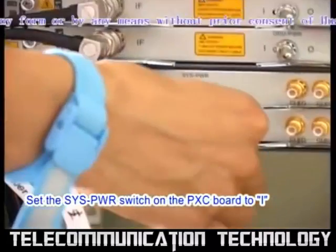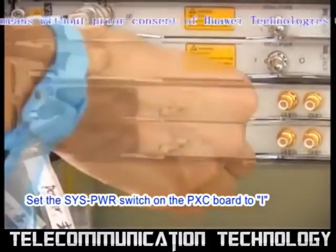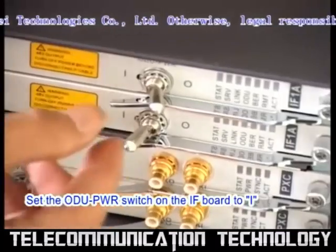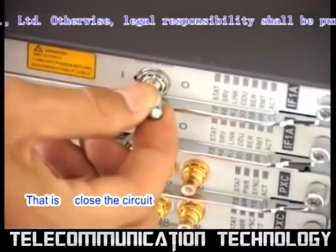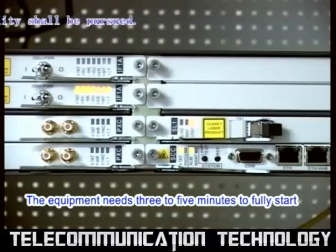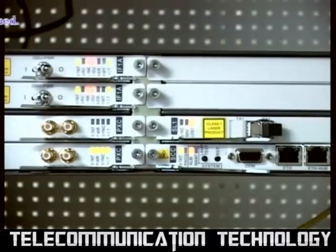Set the system power switch on the PXC board to I. Set the ODU power switch on the IF board to I. That is, close the circuit. The equipment needs 3 to 5 minutes to fully start.